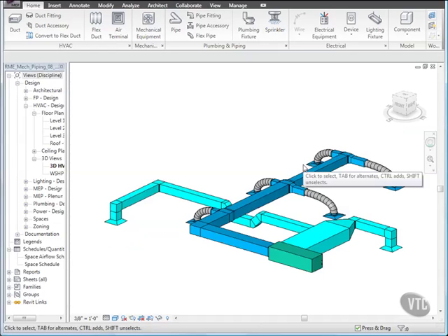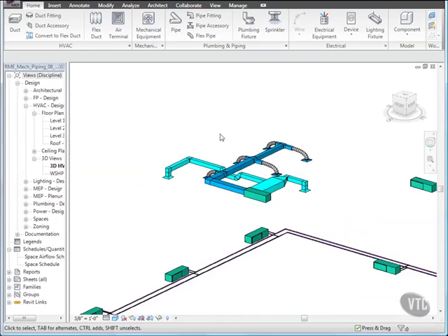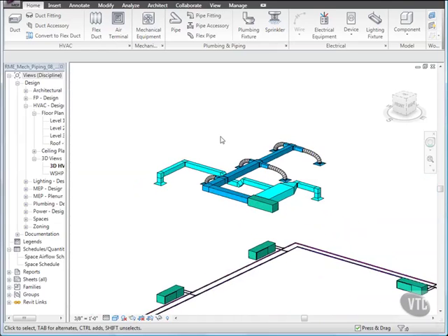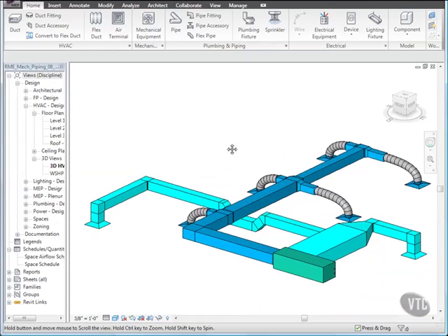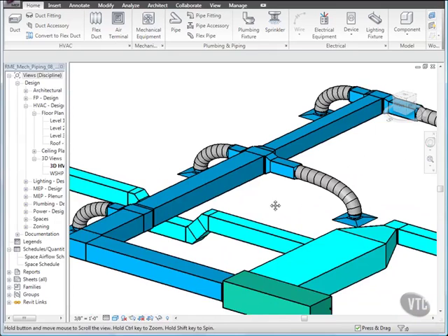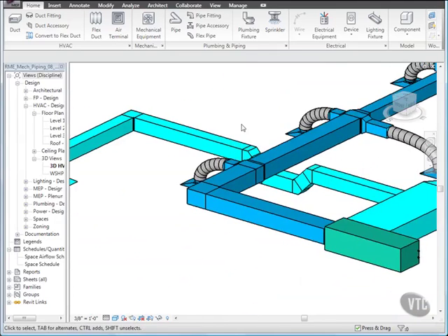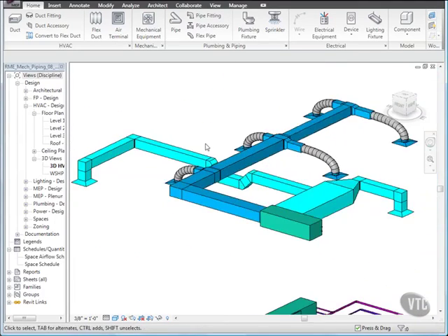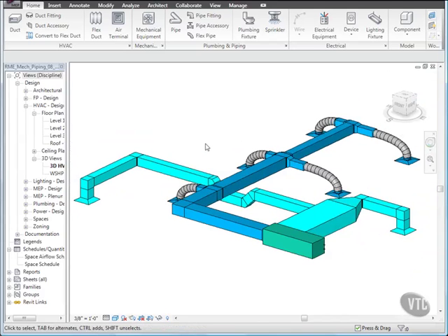If you have a mouse that has a wheel as the middle button, you can roll the wheel towards you to zoom out and roll the wheel forward to zoom in. Clicking and dragging the wheel button allows you to pan the view around. To zoom out to see the entire structure, type the two-letter shortcut ZF.